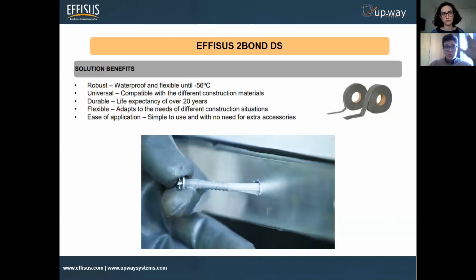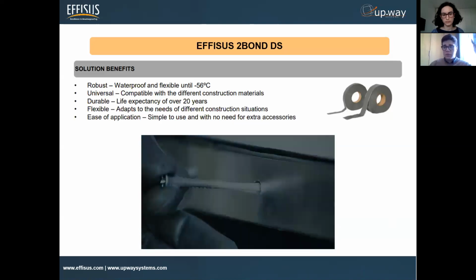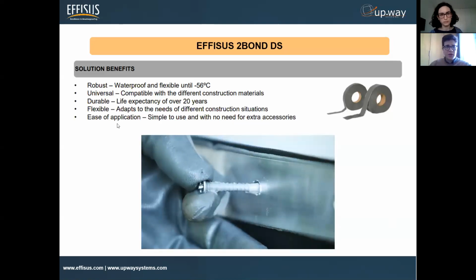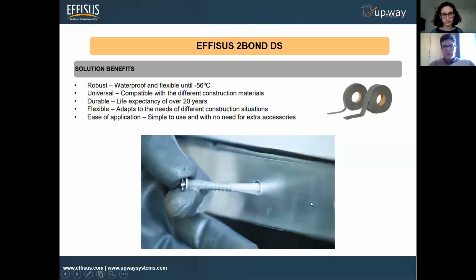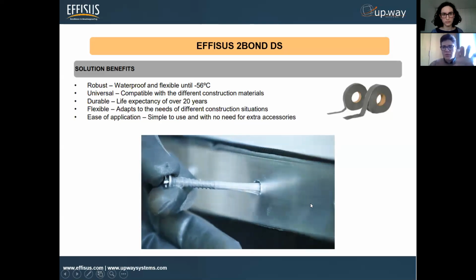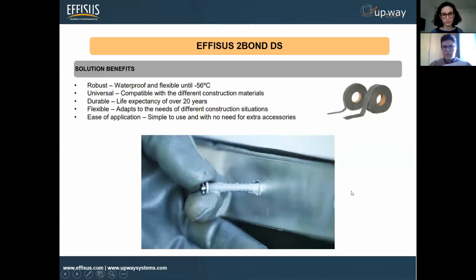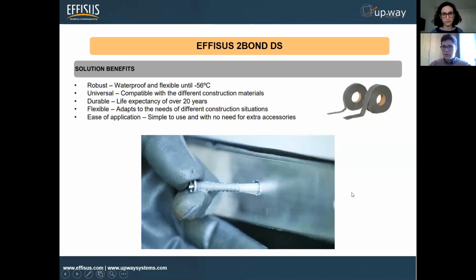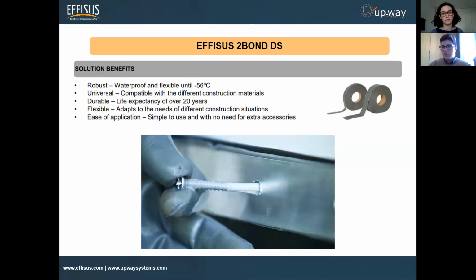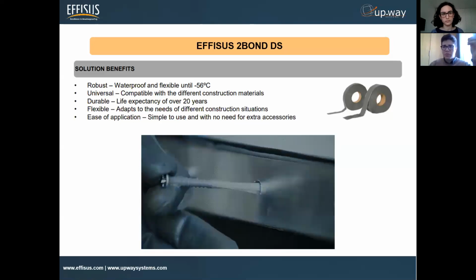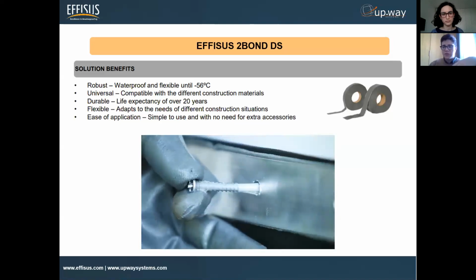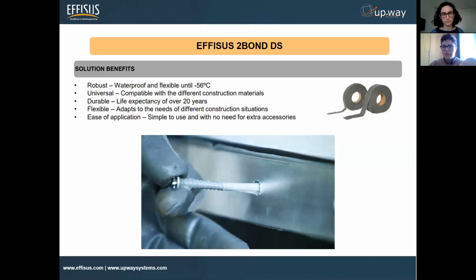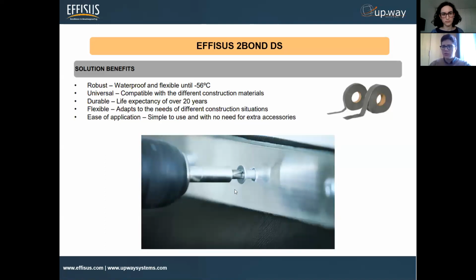And again, you can apply this to multiple situations. You can imagine, we have some specific sessions focusing only on this application of this tape. Today, we decided to focus on specific properties of this type of sealing of fasteners, sealing of perforations on a facade. It could be on a roof. We use this a lot in roofing applications for sealing between joints, for instance, and even roof perforations, where we use this a lot.